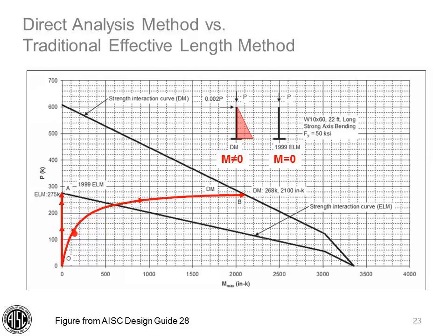Now we increase the column load to 250 kips and increase the notional lateral load to 0.5 kips and rerun our second order analysis. Now our column has substantial moment that didn't show up in the effective length method analysis. Also notice the nonlinearity of the response resulting from the second order effects. Now we'll increase both the axial load and associated notional load up to the column capacity. Notice a large base moment that results that was not captured in the effective length method.